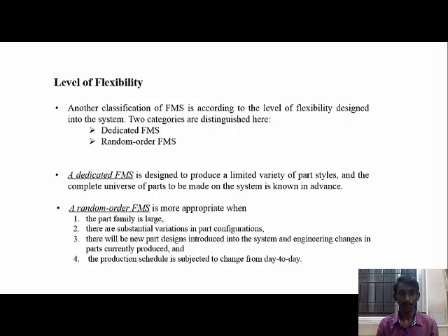A random order FMS is more appropriate when the part family that is going to be produced is large. There are substantial variations in part configurations, new product designs introduced, engineering changes introduced, and the production schedule is subject to change from day to day.